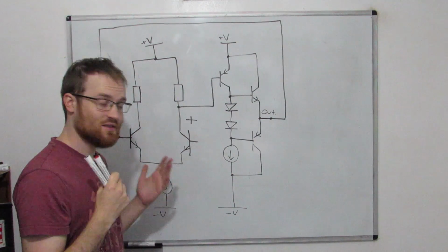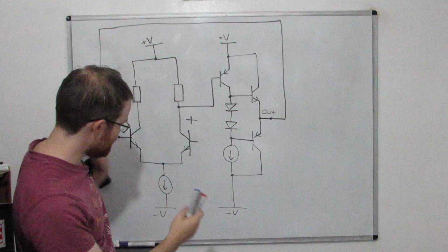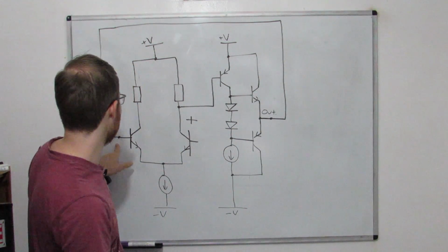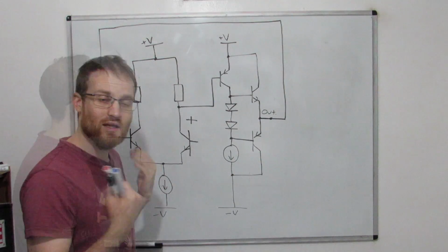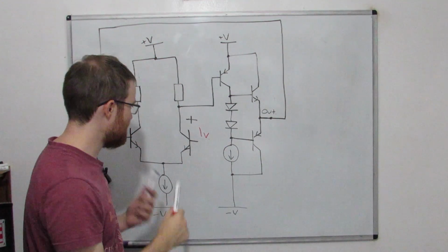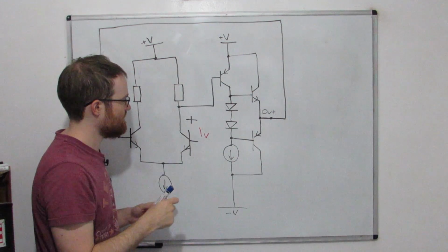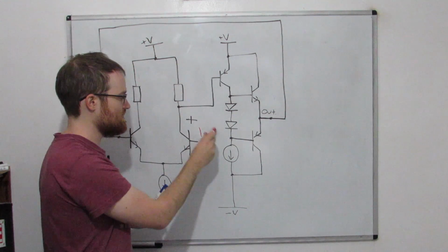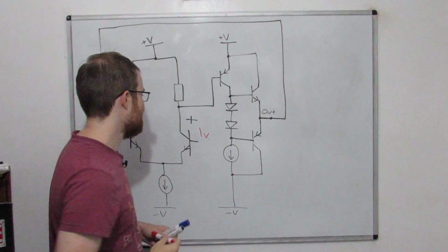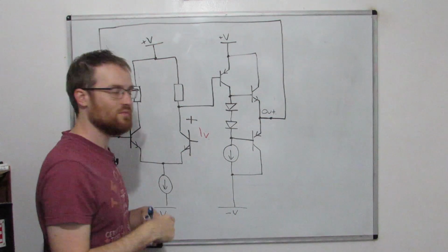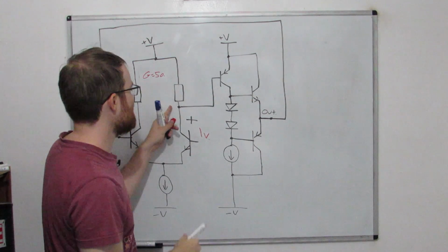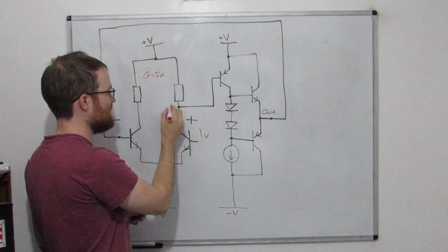So I've just applied that same theory to our simplified internal circuitry of the op-amp. I've got feedback from the output to the inverting input. Let's have a look at how this works. What we know from our differential amplifier is that if I apply a signal to this input, we'll see that signal out of phase at this collector. So we'll see minus whatever. Let's give this stage a gain of 50, a nice round number. So this collector will try to go to minus 50.